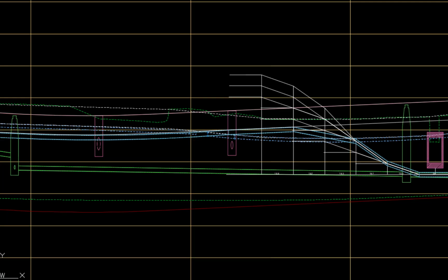After the pipe has been deflected below the RC box, there are some issues with the profile of the water line to the west that need to be resolved. There is currently a sag in the water line around 24+30, which creates a crest or high spot around 25+60. The joint deflection around 26+05 exceeds the maximum allowed 5-degree deflection.